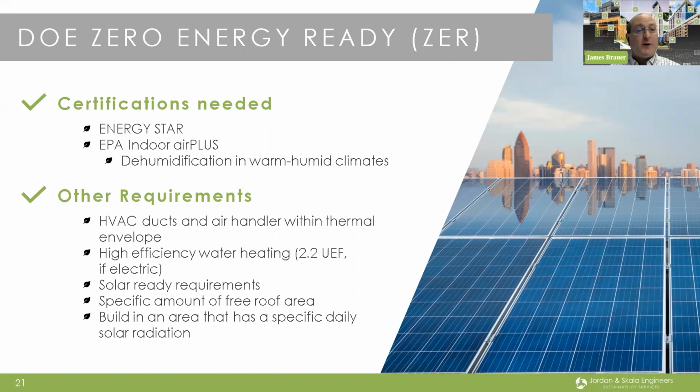Since this is a Zero Energy Ready program, we certainly have to look at solar ready requirements, which also means having a specific amount of free roof area on a south facing angle. And you need to build in an area that has a specific amount of daily solar radiation, so that any solar that does get put on can be very effective in capturing that energy.